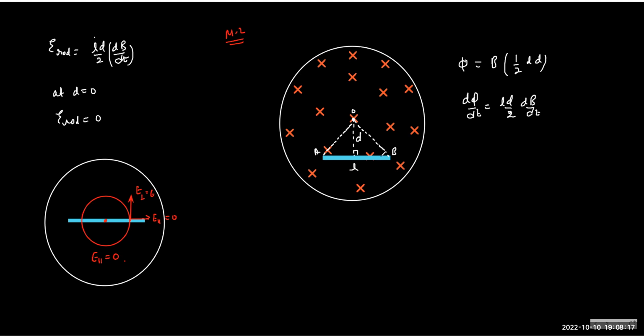Sorry. So you understood how this is done? Yes, sir. The EMF in the rod we can write as L d by 2. And why are we saying this is for the rod? Because the other two parts, OA and OB, even if we assume some connecting loop is present, those two will not contribute to the EMF. So although we are finding it for the loop, we can say this answer belongs to the rod itself. So this idea can apply anywhere.